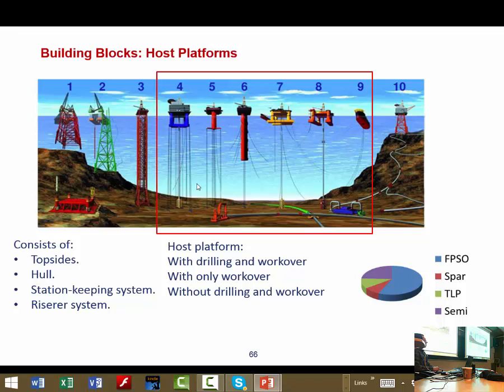So you're just in tension, you don't need any anchor. That keeps you down and limits the side motion. Side motions, exactly. But the others that don't have tension, you have to put anchors. Actually, here the anchors are just some vertical anchors under tension. Basically it's kind of a tension member. The only problem that we have with that is where the well ends up.